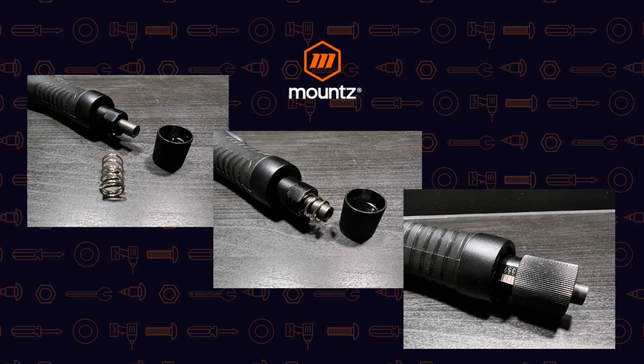And so here's an example of the spring and clutch mechanism that is used on these types of tools. So that spring goes in the nose of the tool, and we can adjust the torque output based off of the spring that is in there. You can dial the nose cone up or down to adjust the torque value.